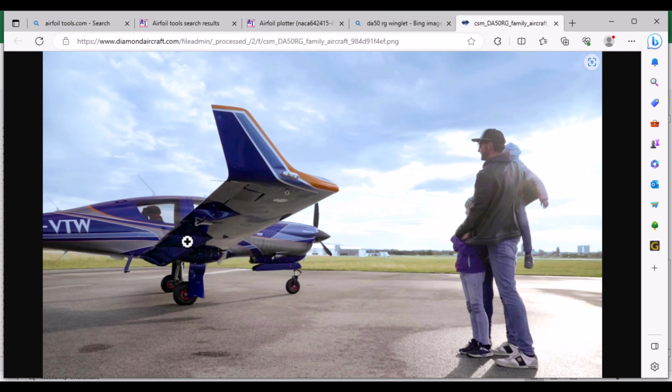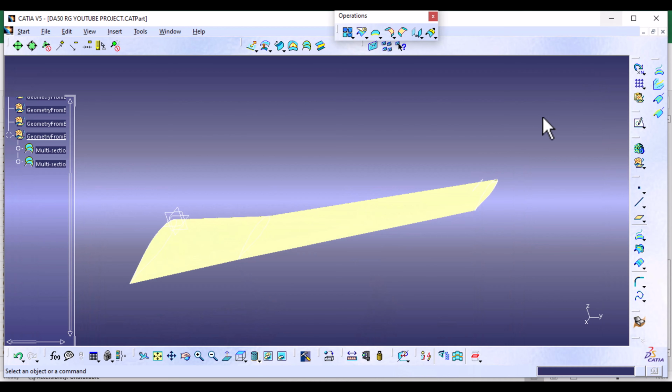So if you look at this, we have plotted these sections on the ZX plane, and now we need to plot this section, which is actually in the XY plane. And you can see that this endpoint right here is kind of just curving upwards, but on the front side, we have this kind of offset, which is going rearwards and also kind of upwards before we connect straight up. So this is exactly what we need to do in CATIA.